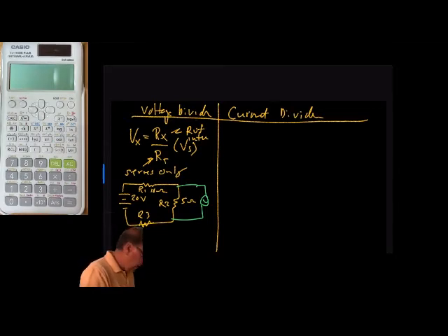So we could say, going around the loop, our total would be 10 ohms plus 5 ohms plus 7 ohms equal to 22 ohms. So then the voltage across R2 would be equal to 5, that's the resistance of interest, which is R2, over 22, times 20, which equals 4.55 volts.